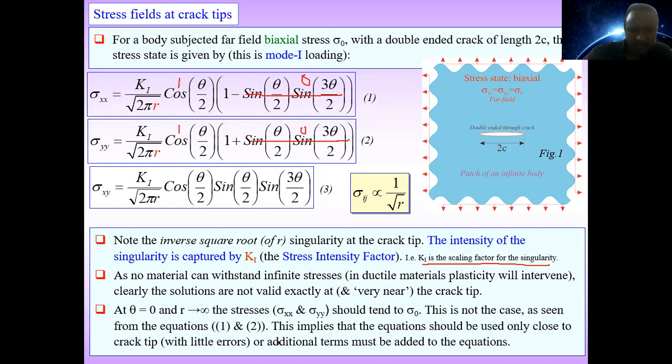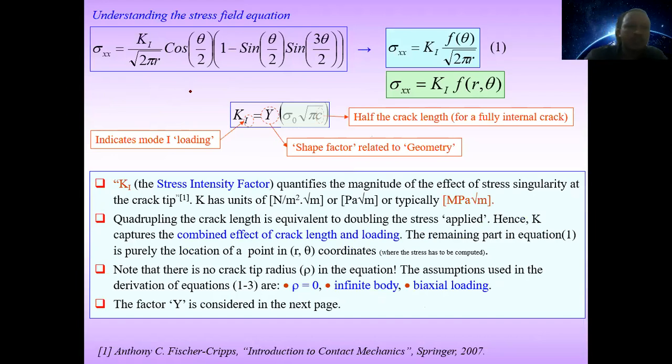So finally, what about that sigma naught? This is not the case, as seen from equations 1 and 2. This implies that the equation should be used only close to the crack tip, with little error, or additional terms must be added to the equation. Okay. So understand the stress field equation.